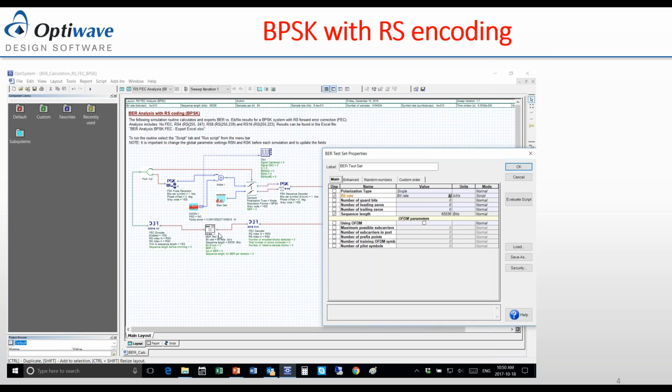But this bit error rate tester here generates the pseudo-random bit sequence. It's built in, the pseudo-random bit sequence generator, and it generates the random sequence, which for us is the information. We add to it the redundant bits to create the error correcting code using the Reed-Solomon code, and then basically we pass it through the pulse generator, which in our situation here is the phase shift keying generator, and then we add noise to it linearly, as you see here.